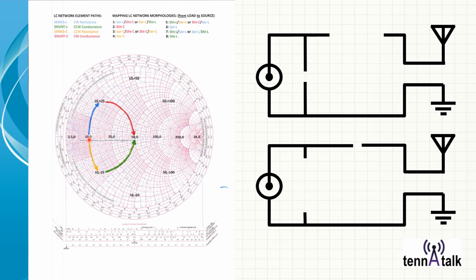So from here, I would navigate clockwise on a resistance circle, and that would mean a series L that looks like that over here. Remember, I'm going from the antenna side and adding it towards the rig side. And then I need to move down a constant conductance circle clockwise.